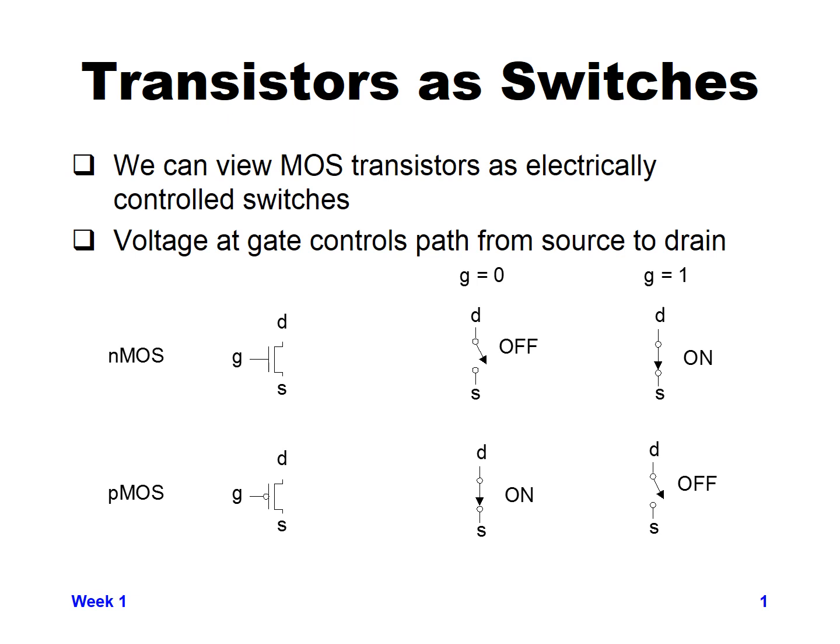consolidated and summarized. So we have an NMOS transistor, which has a gate, source, and drain. Typically we don't show the bulk, we just assume that the body of the NMOS is connected to the source or connected to the lowest voltage, which is ground. And so if we connect the gate to ground and we call the gate value 0, then the transistor is turned off and it's a switch that's off and doesn't allow any current to flow from drain to source.